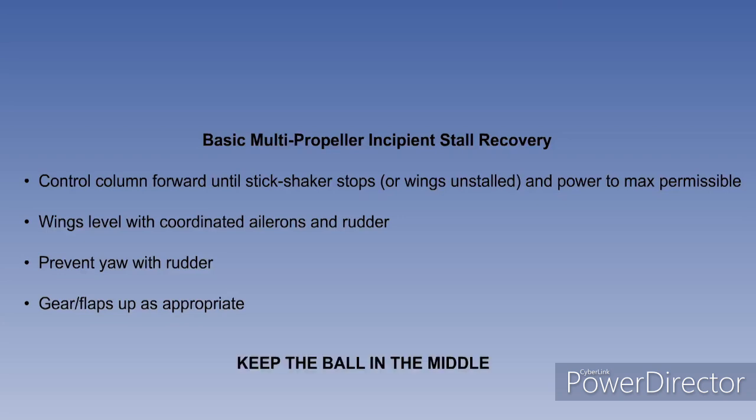The reason for this difference is that the propeller-driven aircraft will experience rapid changes in slipstream and propeller torque during the power increase, and it is essential that the pilot coordinates his control movement during the power change to keep the aircraft in balance. That is, with the ball in the middle. Prevention of yaw is particularly important during stall and recovery.